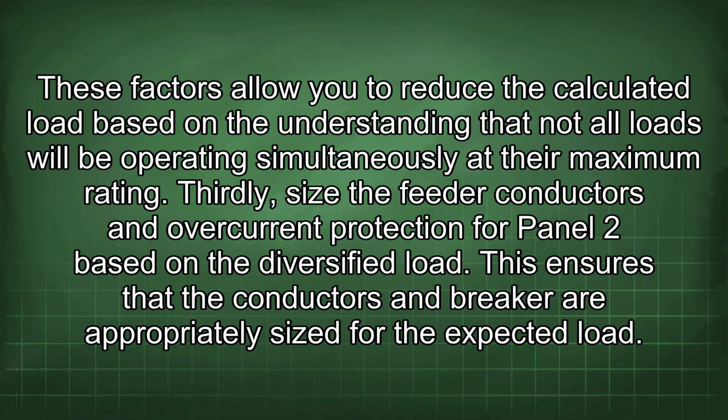These factors allow you to reduce the calculated load based on the understanding that not all loads will be operating simultaneously at their maximum rating. Thirdly, size the feeder conductors and overcurrent protection for panel 2 based on the diversified load. This ensures that the conductors and breaker are appropriately sized for the expected load.